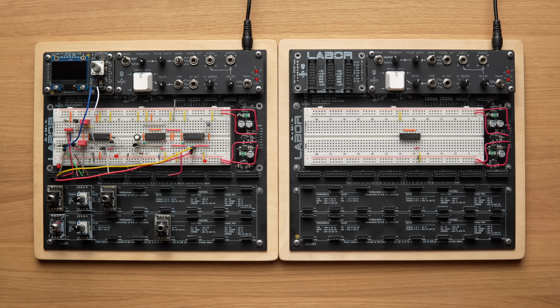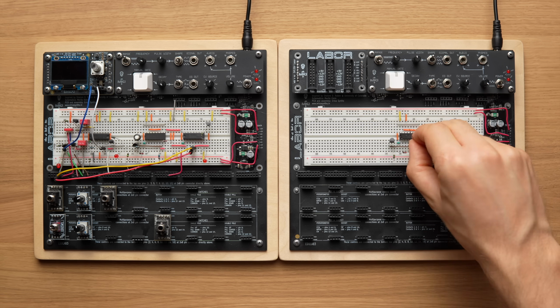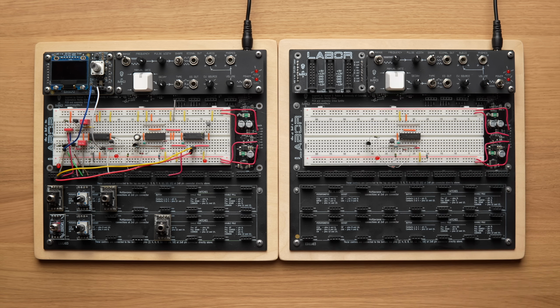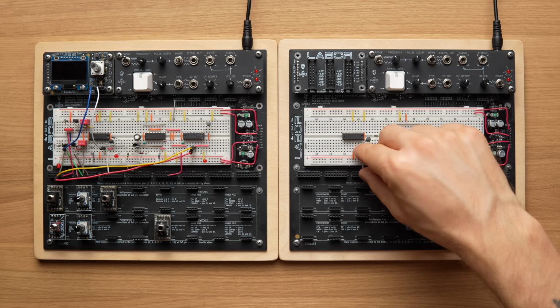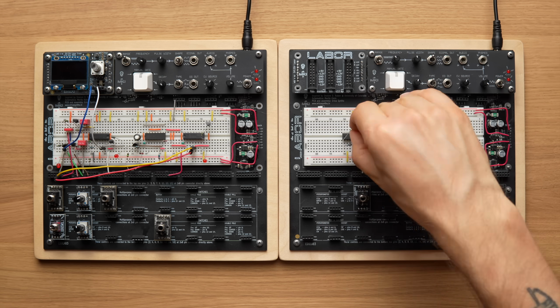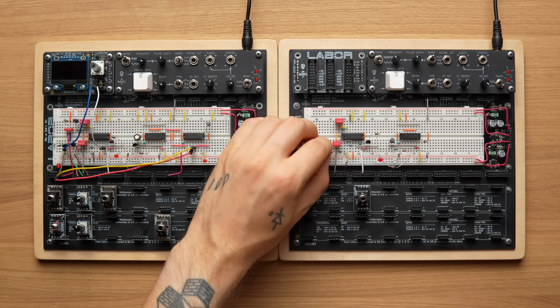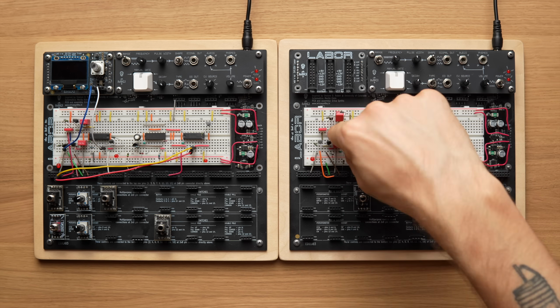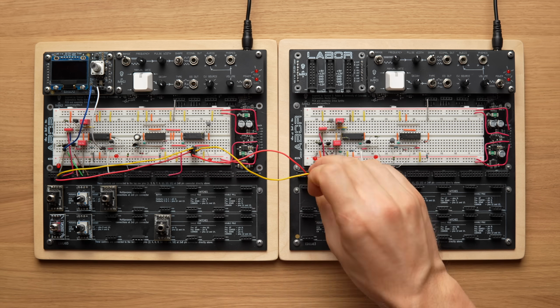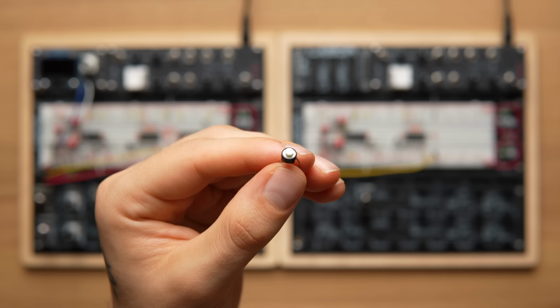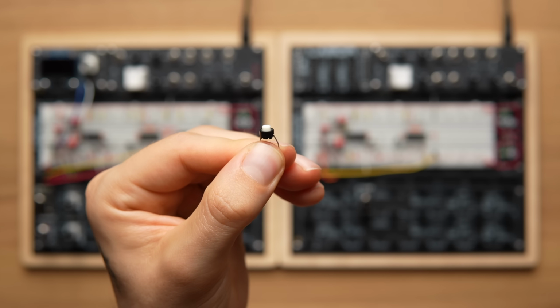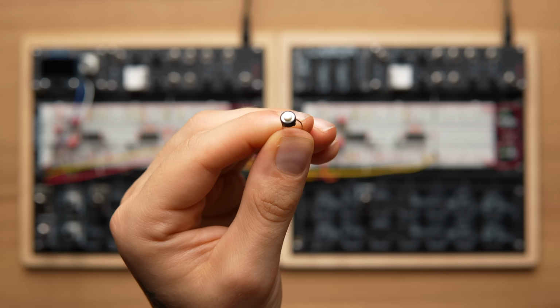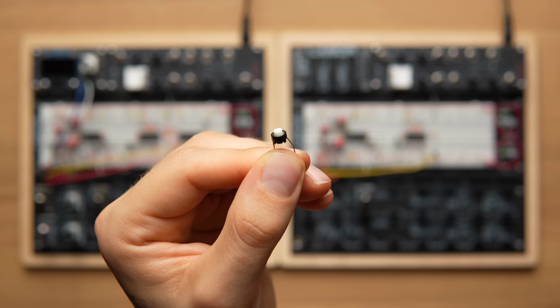Thankfully, our design is so minimal and so modular that we can simply clone the sections we need. To get a second trigger pattern, we'll simply double the 4015 based tap looper. And for an additional accent sequence, we'll set up another synced LFO. There's just one small and slightly silly problem. I don't have a second breadboard-friendly push button for clearing steps, but maybe that's a good thing. It gives us an excuse to simplify the interface even more.